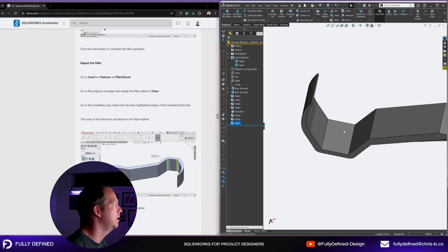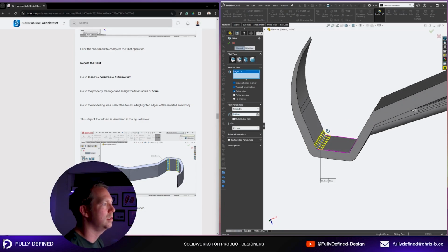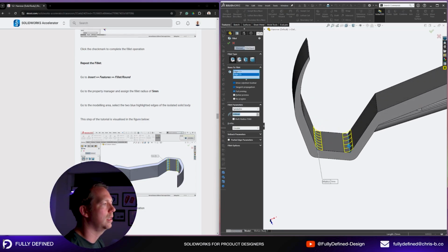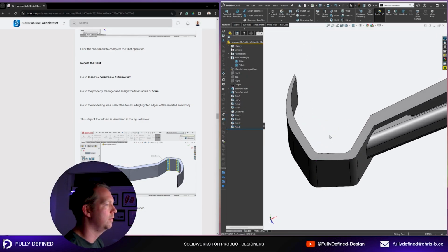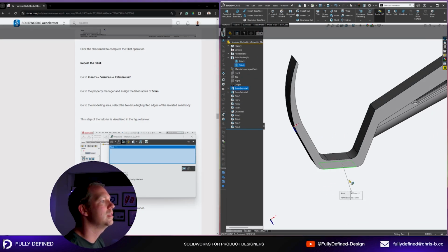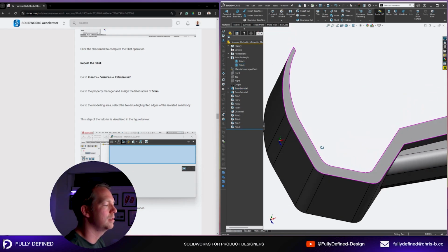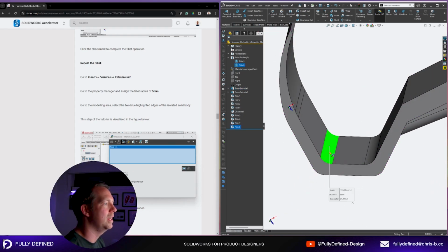More on the inside. Okay, now look, these are some design suggestions. If I was designing a product like this, I would look at the wall thickness. So let's say the wall thickness there is 5mm. Now, whatever I had for my internal radius, my external radius should be the internal radius plus the thickness.